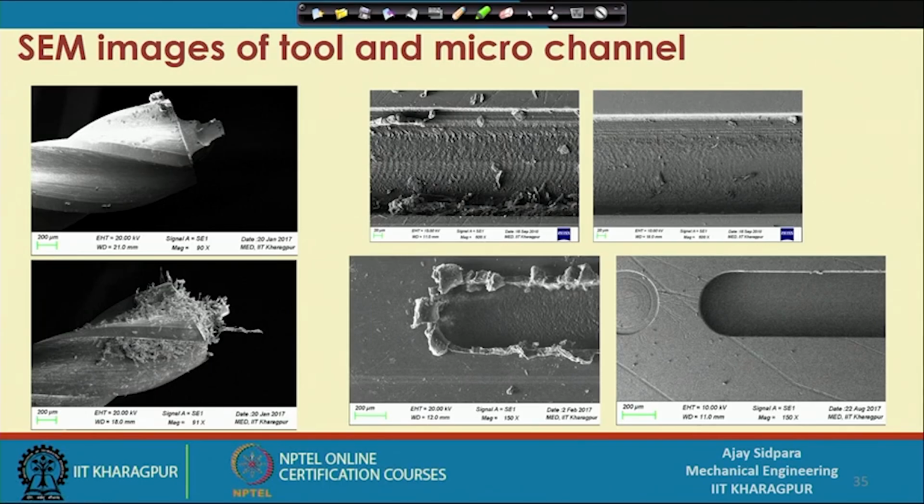So, you do not need to use the interferometric-based method which we have seen earlier, where there was the view of the grinding wheel topography and the ground surface. Those types of surfaces you can get by SEM also, but you need some dedicated software which is available in the market. So, SEM, 3D topography measurement by interferometric-based or laser confocal microscopy, these two instruments and the microscope at very high magnification, even for different, less depth of cut, are still useful for monitoring the system in different machining operations.